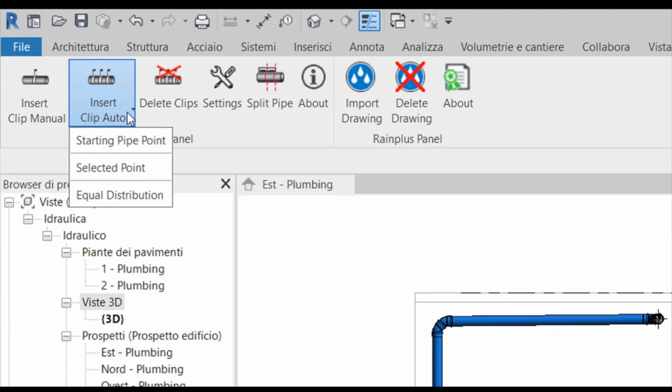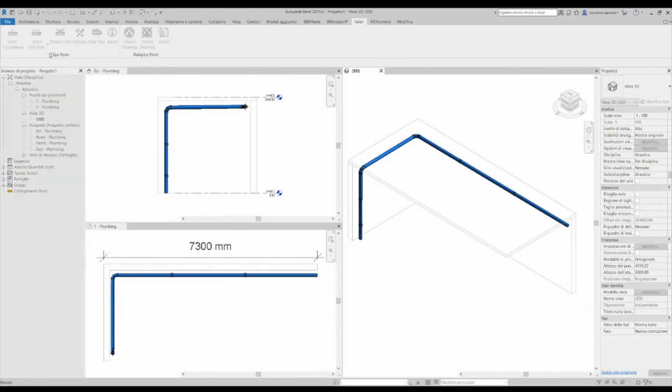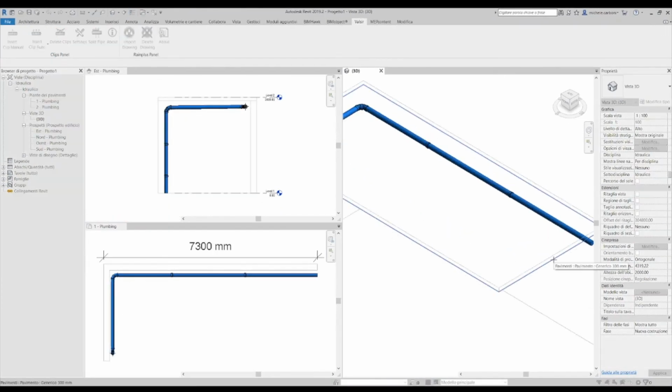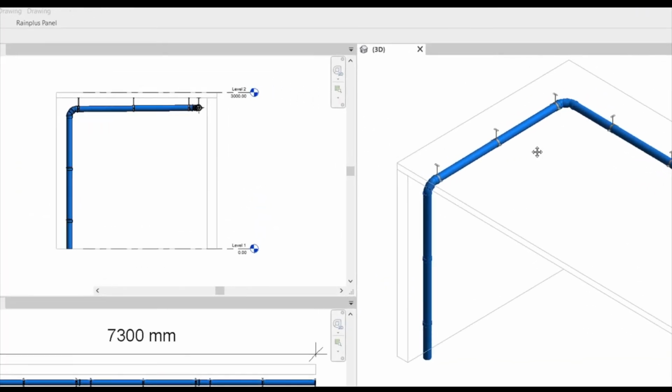If you remember, since we have used the option Attach the clip to the support if possible, we have to select a support surface. In this example, we'll select our concrete horizontal slab. Then we have to click on the pipes, and we are going to see that automatically the application is adding all the clips. If you have a pipe with a slope, since we are selecting the option Attach the clip to the support if possible, the application is calculating automatically the distance and the length of the rod between our clip and the support surface. This is another advantage of using the clip tool.